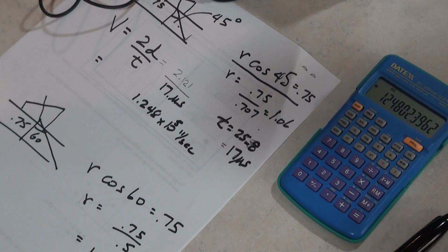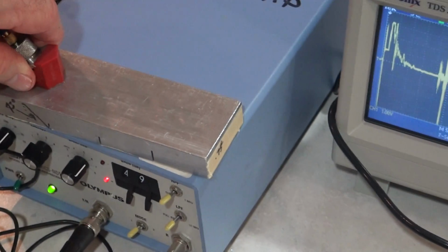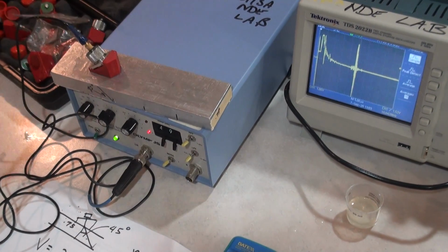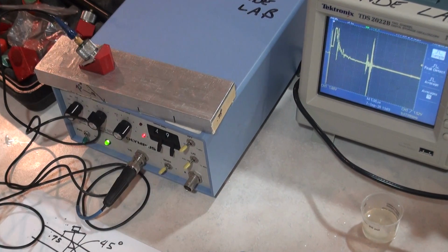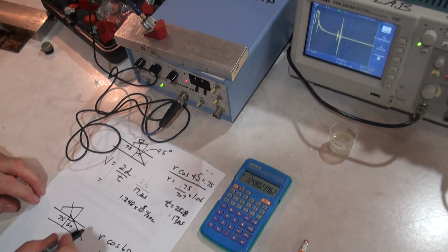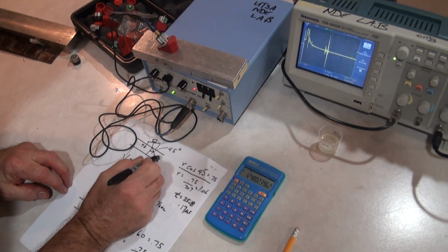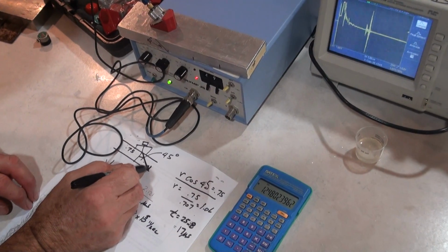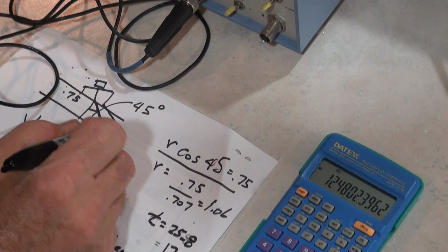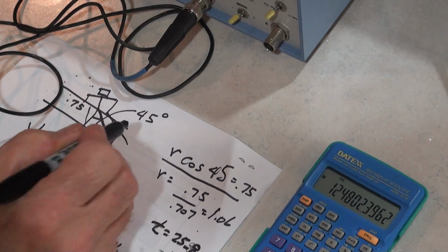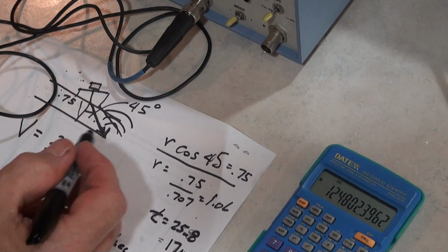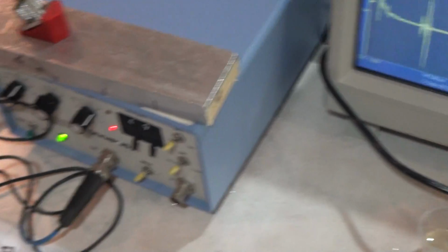Now the other thing that's interesting about this is if you look at this, there's a signal that's right in front of there, okay? And that's caused by the diffraction from the tip of the defect, okay? So if I look at my defect here, the biggest signal is from this edge here, from the corner. We call that the corner reflector. But the wave is actually spreading out from the wedge, so it's hitting the top of the defect, so it's putting out diffracted signals, and so that is what that signal is, a diffracted signal.